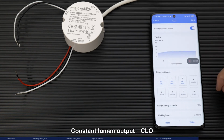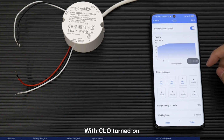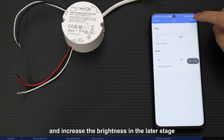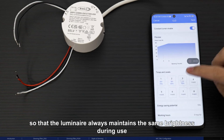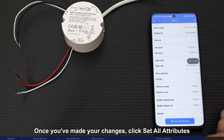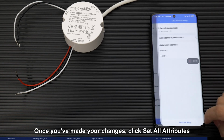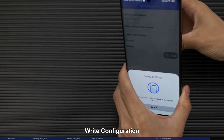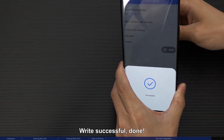Constant lumen output, CLO. With CLO turned on, the driver will automatically reduce the brightness in the early stage and increase the brightness in the later stage, so that the luminaire always maintains the same brightness during use. Once you've made your changes, click Set All Attributes. Align the position of the NFC component. Write configuration. Write successful, done.